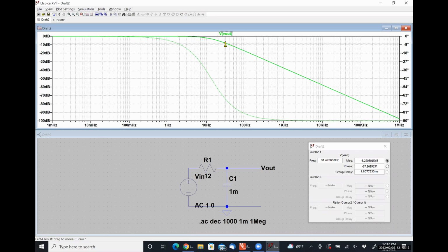All right, so when we resume on Friday, we'll start to look at second order filter circuits. Technically, there are still 3 more first order filter circuits that we could look at. So we could swap R and C to observe that we get a high pass filter. And then we can do RL circuits and find out that we get a low pass filter and a high pass filter. I'll probably make you do that for your homework. It's a waste of time in here. We'll get to second order circuits like band pass and band stop filters on Friday.